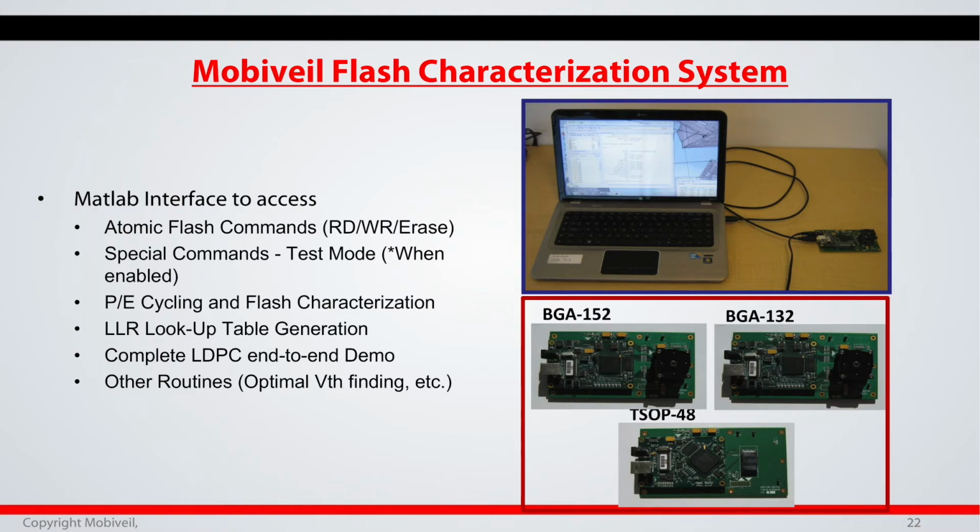And this is what is also ported to this IoT platform you see. And then this is another platform. This is for flash characterization. If some of you are flash guys, you know how difficult it is to characterize flash. And this is what we have built through a MATLAB interface. You do a lot of PE cycling to characterize the flash, because finally your end goal is a real LLR lookup table. You want to look at the end-of-life requirement, do that analysis, and figure out the best LLR based on how you have to program the flash to operate it.